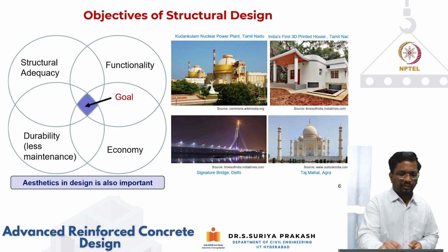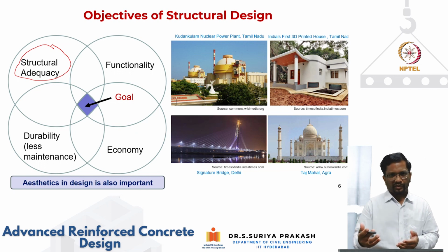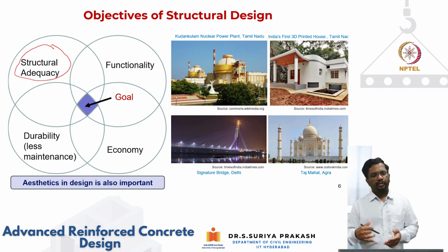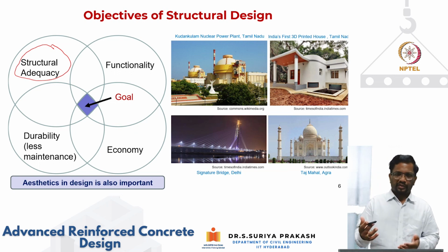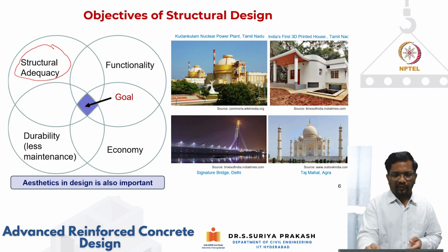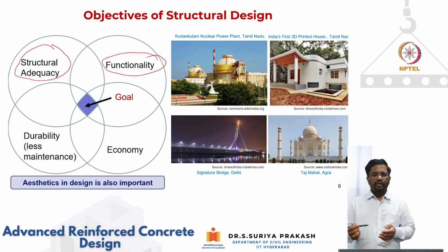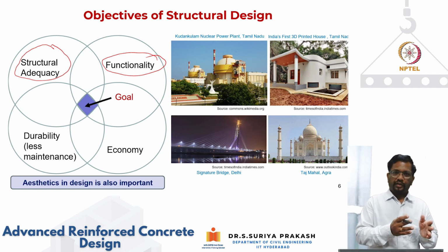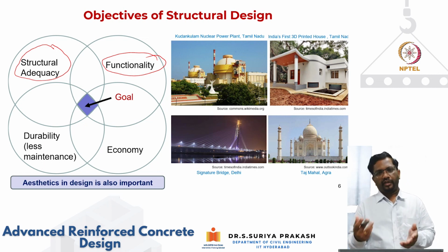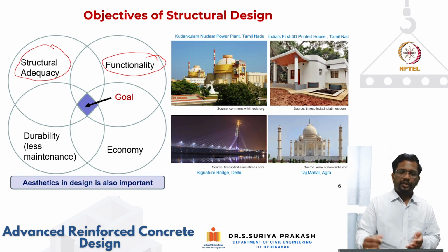So the structural adequacy, I think we talked about: it should satisfy the safety requirements, that is the strength requirements, and then the serviceability requirement. The structure also should be stable. So these are the things that we talked about: structural adequacy, and then functionality. Okay. So again, functionality is very, very important. If the structure meets all the three requirements but is not functional, then again it is not going to be a good design, right? And it should also be durable.